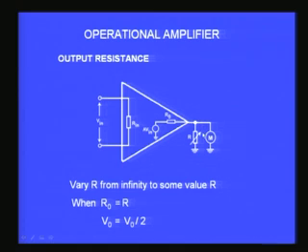Now, after measuring that V naught, I introduce this resistance and I start varying it till I get V naught exactly half of the previous value, without altering any of the other input voltage or resistance, etc. So, when that happens, you can see from the equivalent circuit, the voltage source is now connected in series to two resistors RO and R, which is connected outside. If this R is not present, I get VO, which is the actual value of the A V in, the total voltage of the voltage source.